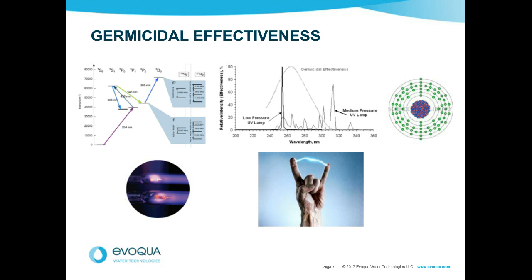If there's chlorine, there's probably chloramines as well. So we would tend to lead with medium pressure for a dechlorination or dechloramination application, just because those chemicals absorb UV more, more resonance occurs, more bonds get broken. So it's more likely to work if it's a medium pressure system than if it's a low pressure system. So yes, we would prefer medium pressure for those photolysis type applications.